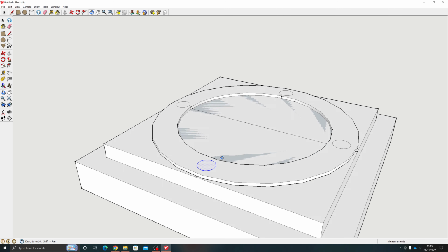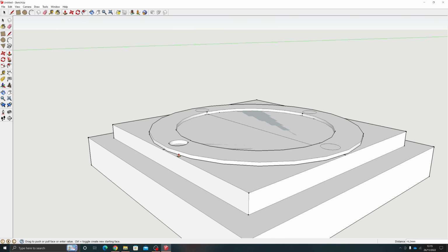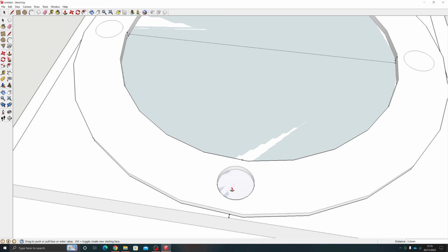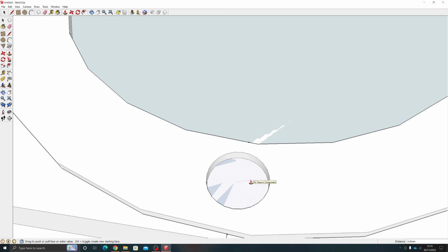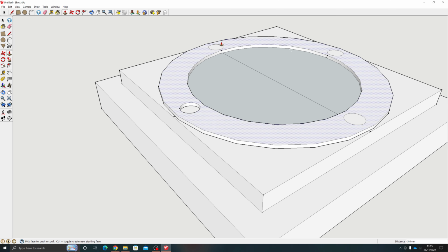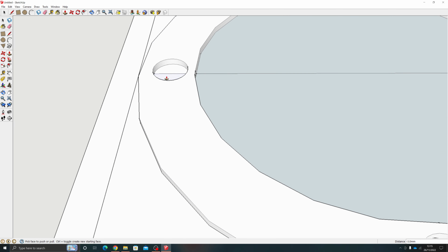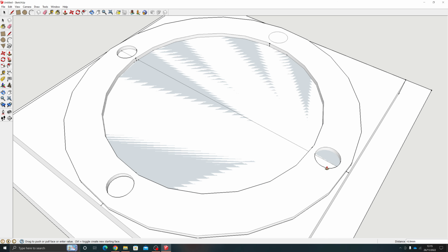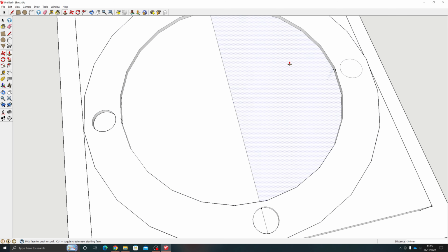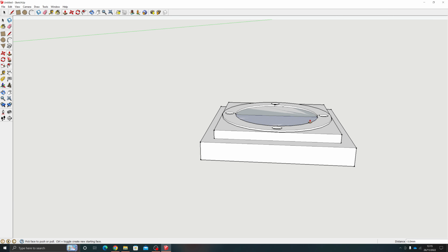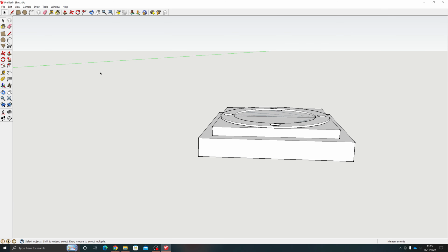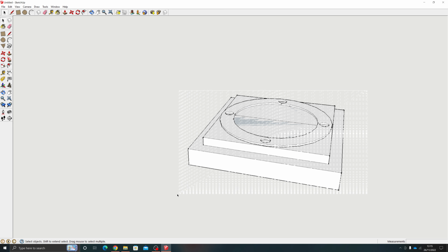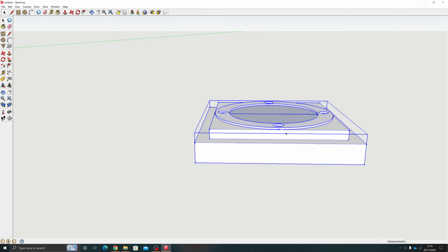What I'm then going to do is extrude downwards, and I want it to cut all the way through. So again, you'll see that it goes on face a component, and you should see that it wants to get rid of it, because I actually want to delete that. Most of these things are visual, but I like them to look more realistic in how it's actually going to look for my real design, because it gives me a much better idea of what I'm going to create, and I can see problems before they arise. That's kind of the point of this, you want to see things that aren't quite right.